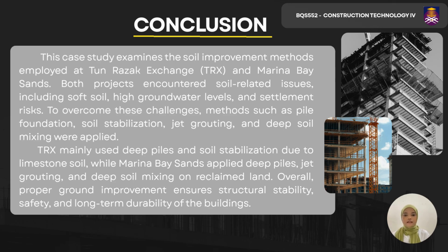In conclusion, this case study examines the soil improvement methods employed at Tun Razak Exchange and Marina Bay Sands. Both projects encountered soil-related issues, including soft soils, high groundwater level, and settlement risk. To overcome these challenges, methods such as pile foundation, soil stabilization, jet grouting, and deep soil mixing were applied. TRX mainly used deep piles and soil stabilization due to limestone soil. Marina Bay Sands applied deep piles, jet grouting, and deep soil mixing on reclaimed land. Overall, proper ground improvement ensures structural stability, safety, and long-term durability of the building.